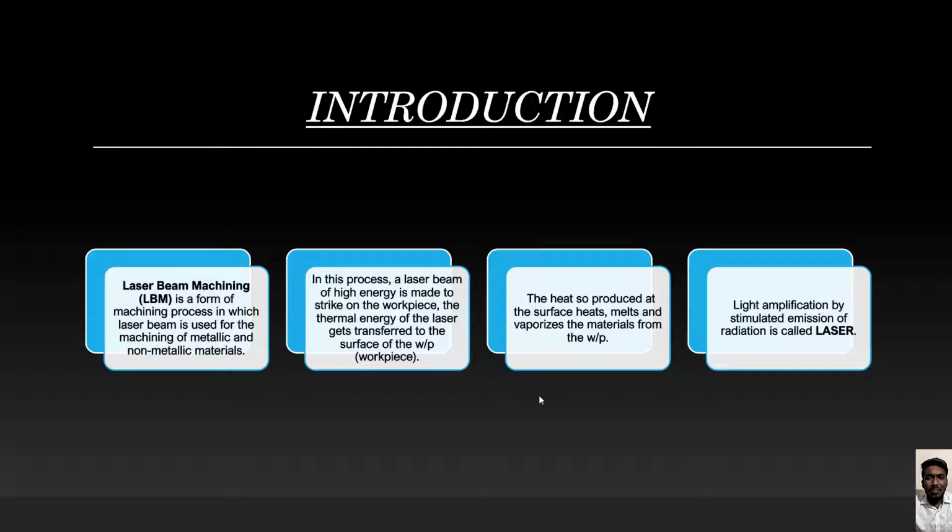Laser beam machining. First, let us discuss machining. What is machining? Machining is nothing but the conversion of a raw material into a final product with desirable shape and size through removal of material. Laser beam machining is a thermal process. The removal of material is done by laser beams. It is applicable to both metallic and non-metallic components. In this process, a laser beam of high energy is made to strike on the surface of the workpiece.